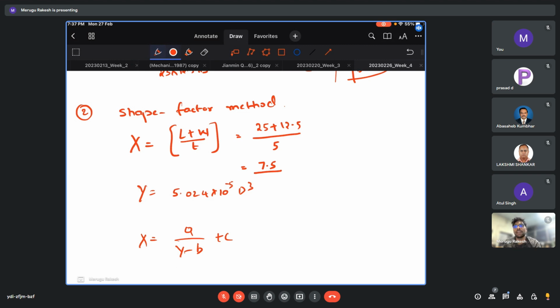Then finally, they are also asking us to include the volumetric shrinkage of the solidification. So that is not 3 times the shrinkage concentration alone. So we have 3% shrinkage, so we have to take 3% multiplied by 3 times since it was given. So total 9% extra we need to get.